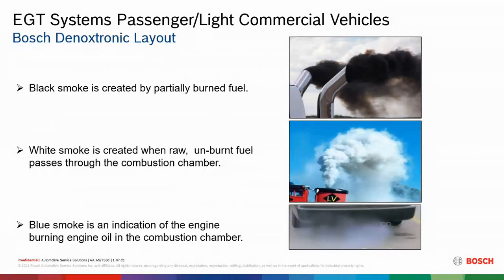And also the white smoke: cold engines, typically older diesels, you always saw a little bit of white smoke on a cold engine, especially on cooler days, of that raw fuel just being sent out until it warms up. It usually goes away. But if there's a cylinder just totally misfiring, not firing at all, you can still get that white smoke of unburned fuel.